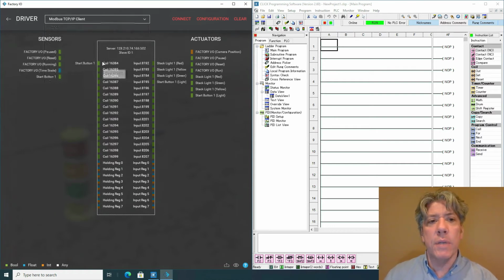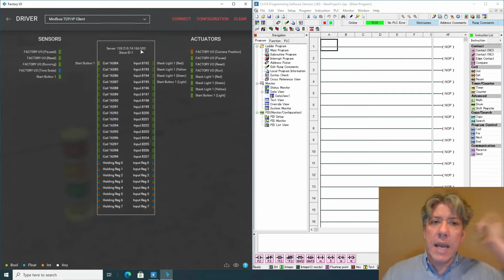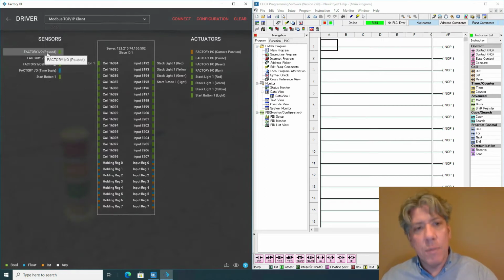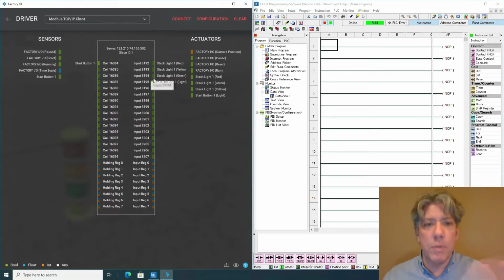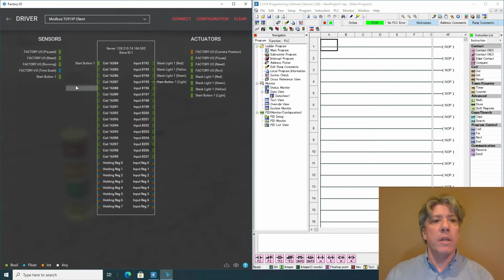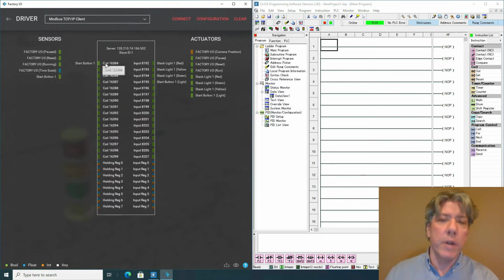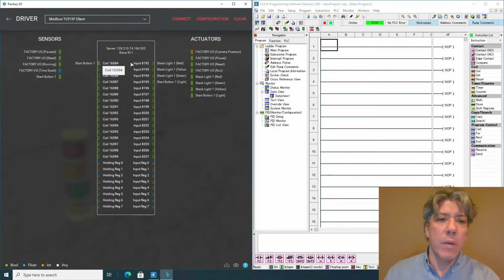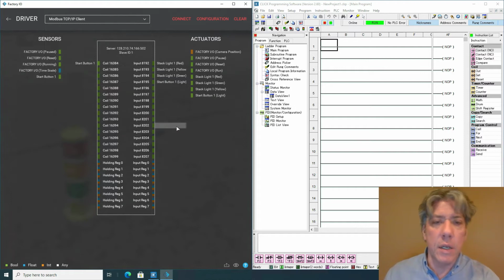And it's a little confusing because you see coils here, and this is the IP address, for example, of the PLC. And so it looks like they've got outputs here because you would consider those coils, and inputs over here. So you feel like you need to connect Factory I/O input devices like this button to the input side. But that's not the way it works. Basically what they're saying is that this button is going to trigger an internal coil in the PLC, turning that input on, which actually makes sense. Why they call this input, I could go into that. It doesn't matter too much.